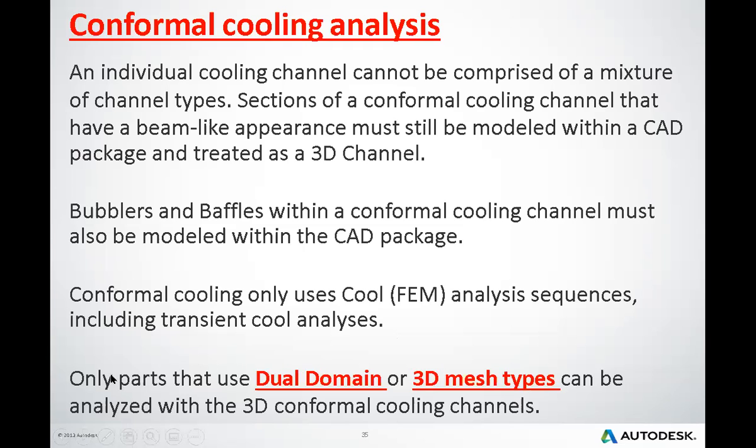And okay, in the last paragraph, I want to emphasize this because only parts that use the dual domain or 3D mesh type can be analyzed with the 3D conformal cooling channel. Okay, we have to use this information.